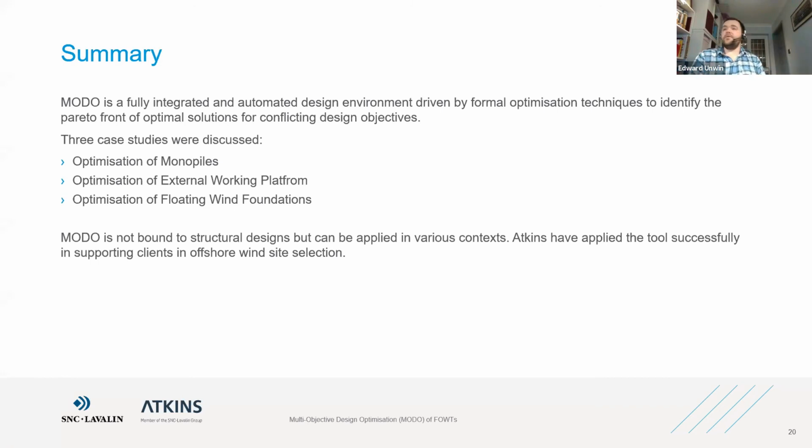We would stick with some of the more conventional ones: a stability model and a hydrodynamic model for the motions, and some structural models, but there'll be separate models all within the same design environment. So they'd all be interfacing with each other to produce a design, but it wouldn't be a single model that covered all of them, and particularly not a surrogate model.